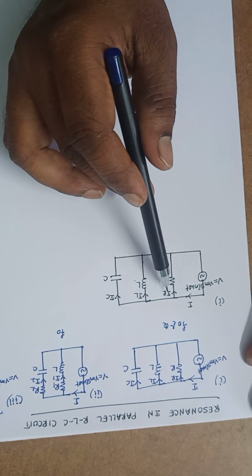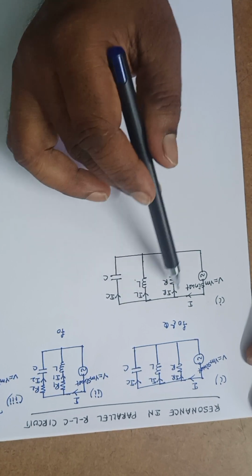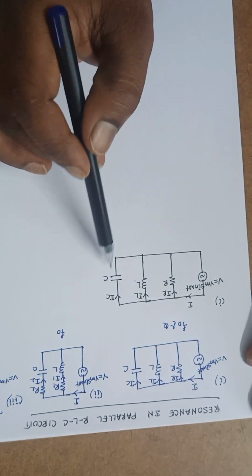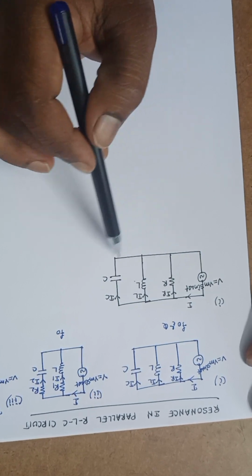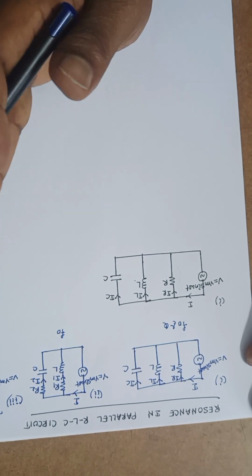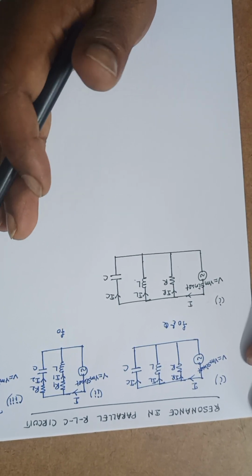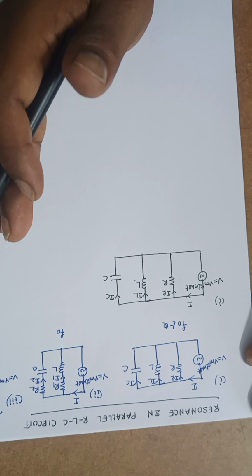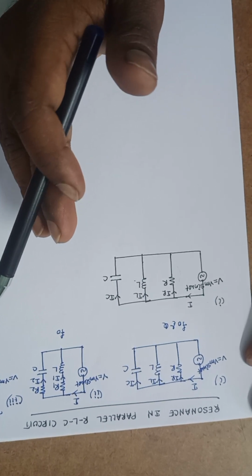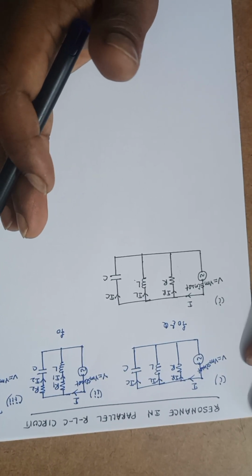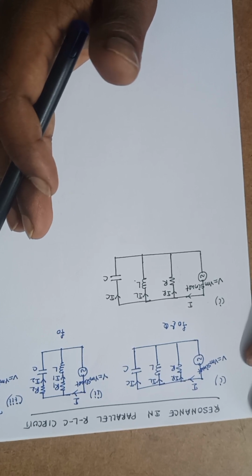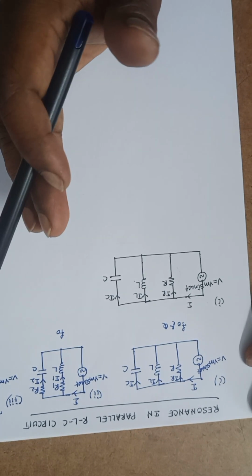For this parallel combination I need to find one equivalent impedance, and again I need to use another formula R1 R2 by R1 plus R2 to calculate the equivalent impedance offered by this circuit. So finally what I want to say here is, if there is a parallel RLC circuit, find the admittance and make the imaginary part of that admittance equal to 0, so that you can find the resonance frequency. If it is a series RLC circuit, better to calculate the impedance and make the imaginary part of that impedance equal to 0. From that you can get this resonance frequency.